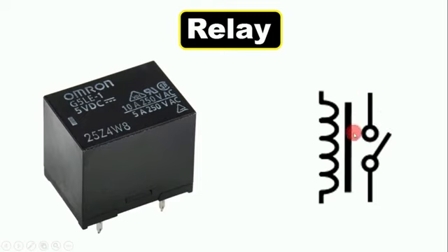So what we can do is connect any power supply here. Like in this relay here, a 10 ampere 250 volt AC connection can be made. So in this contact, up to 250 volt we can provide and up to 10 ampere current can easily flow. Our circuit and electronic components will remain unaffected.